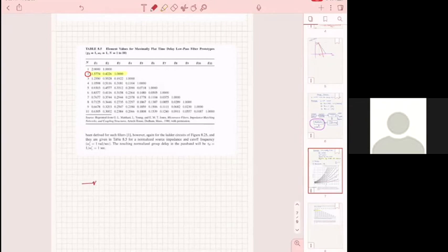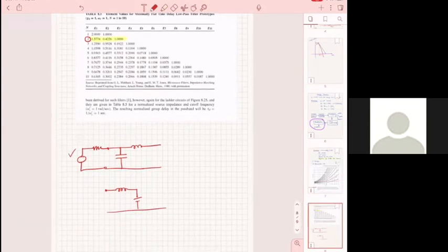If this is the resistor of my source, then I have a selection either to start with the capacitor immediately, or to start with an inductor and go inductor, capacitor then. The idea is that if I have a voltage source, I'm always starting with a capacitor. If I have a current source and then a resistor parallel to it, then I'm always starting with an inductor.